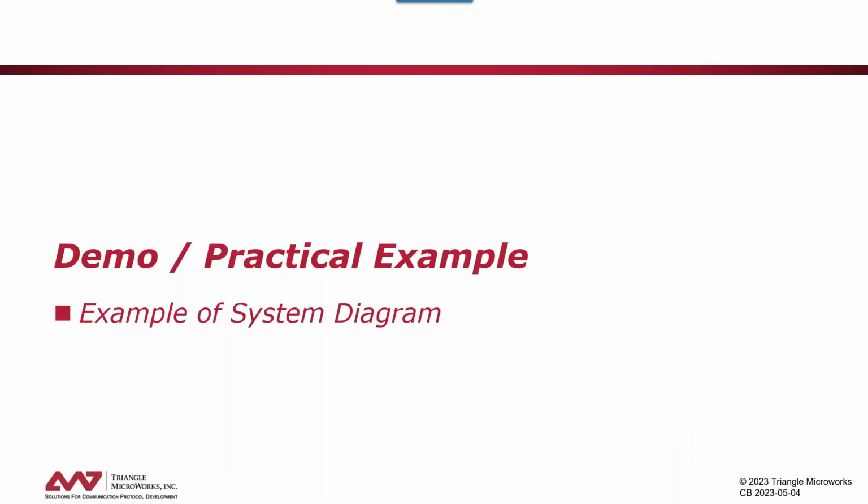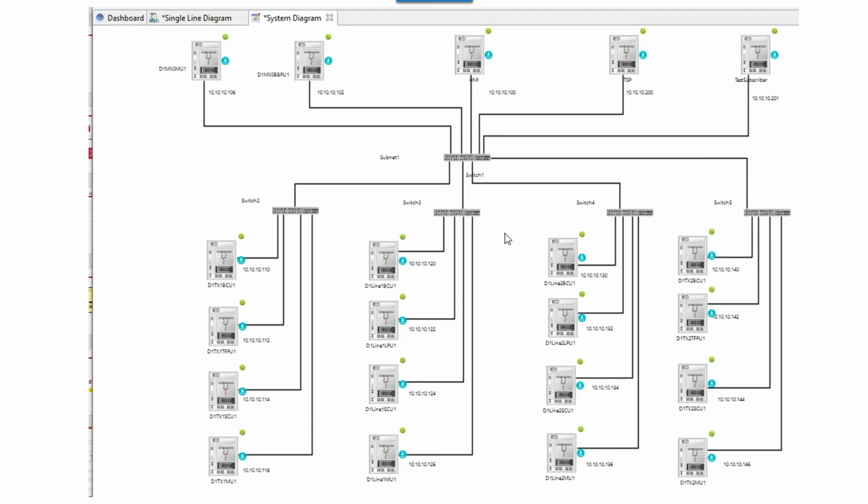So again, how does this look in our project? And I have again a little screenshot here. If we go back to our project now, as an end of this step, we have our system drawing or comms drawing, where we see the different IEDs connected to networks. We have here 1 switch per bay. In a bay, we have the 4 IEDs, starting with the merging unit, the switch control interface, the protection device, and the bay controller, and we have that in all bays.